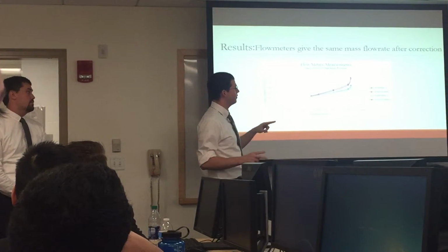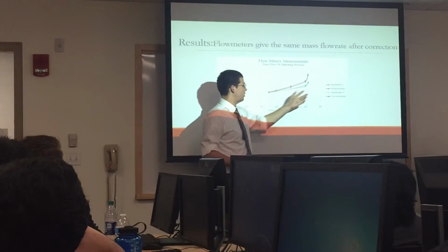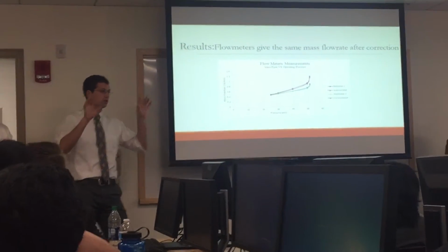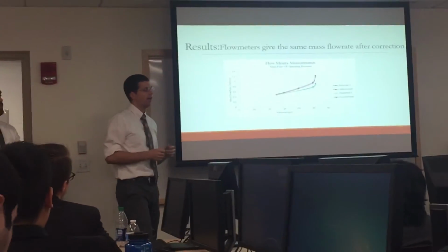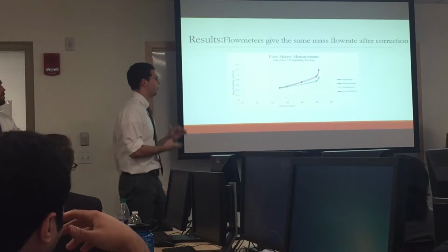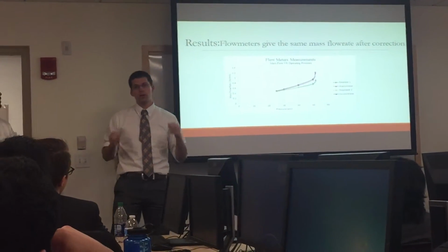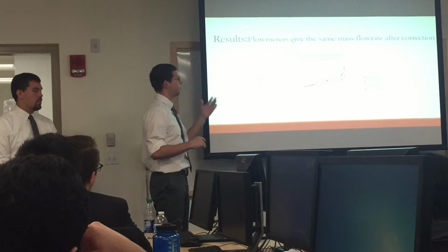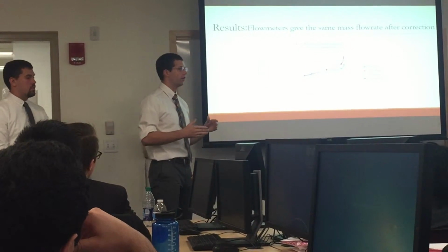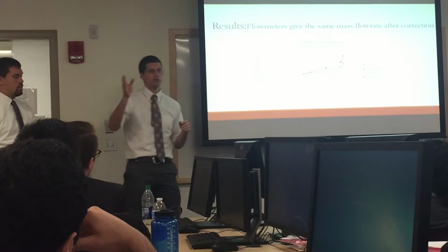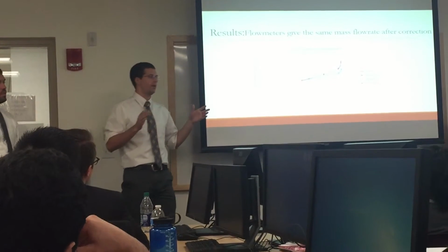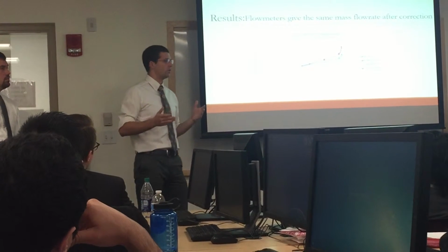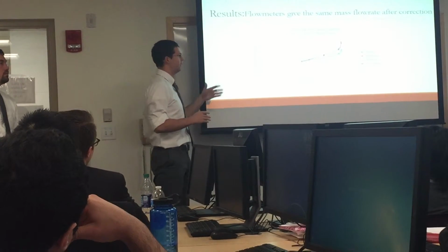And so there's two groups. One are the rotameters, and those are very accurate because we took the pressure from the pressure gauges right at the rotameters. We know where those are. However, for the Coriolis meter and for the anemometer, we didn't have exact pressures for those locations. So in our calculations, we used the pressure at rotameter 2. However, there is a pressure drop between the pressure gauge for rotameter 2 and the Coriolis and the anemometers. We could kind of guess about that pressure drop, but in the end, we would just be force-fitting our data to fit the other ones.